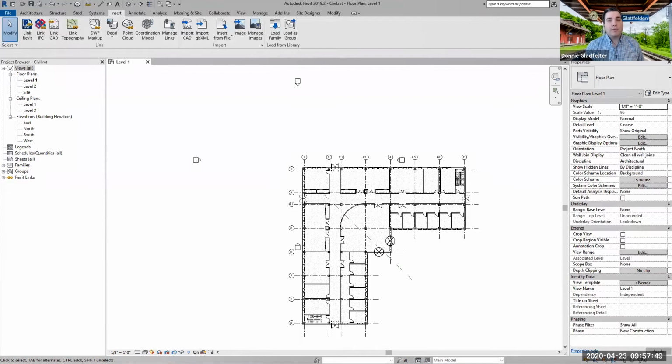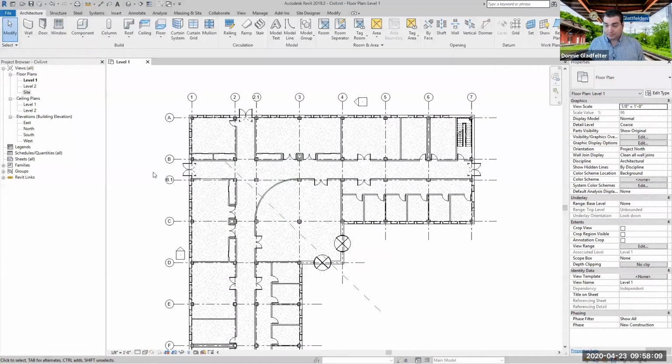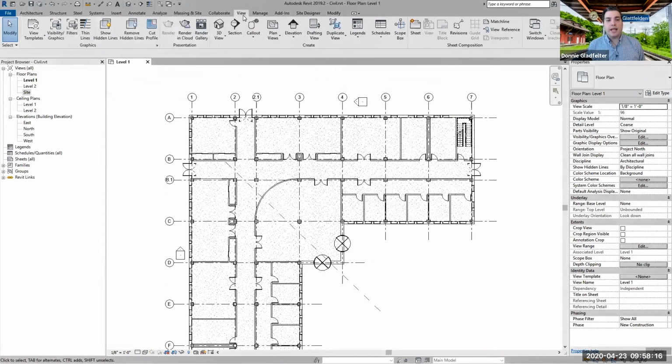And so from here, this is where we're going to begin applying those real world coordinates inside of this model. The net result is going to be that we'll be able to link the civil model back into Revit, and from there, begin importing all of the stuff from Civil 3D. So with that in mind, what we're going to do now is import the coordinate that we exported from Civil 3D.